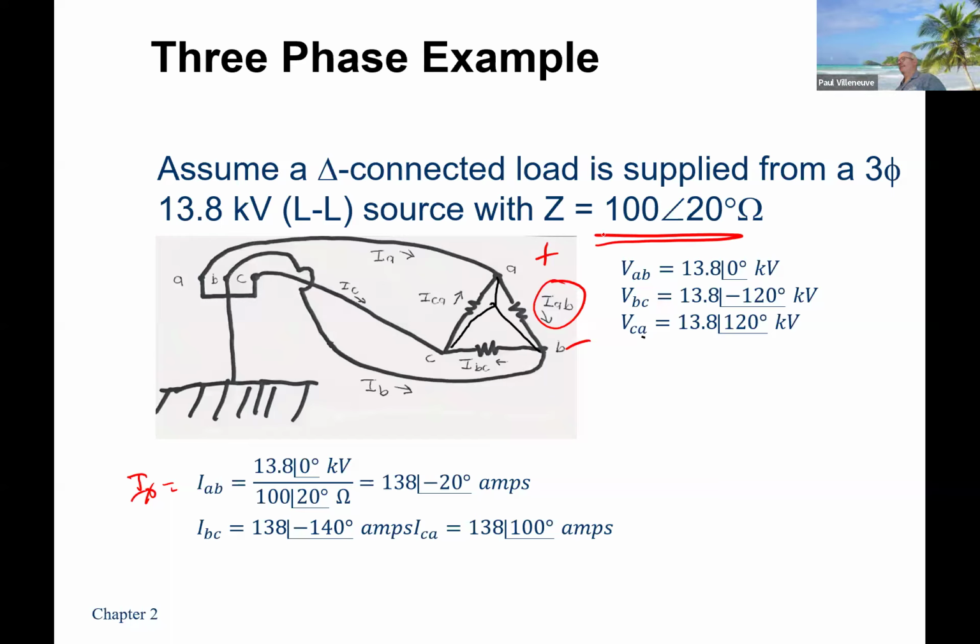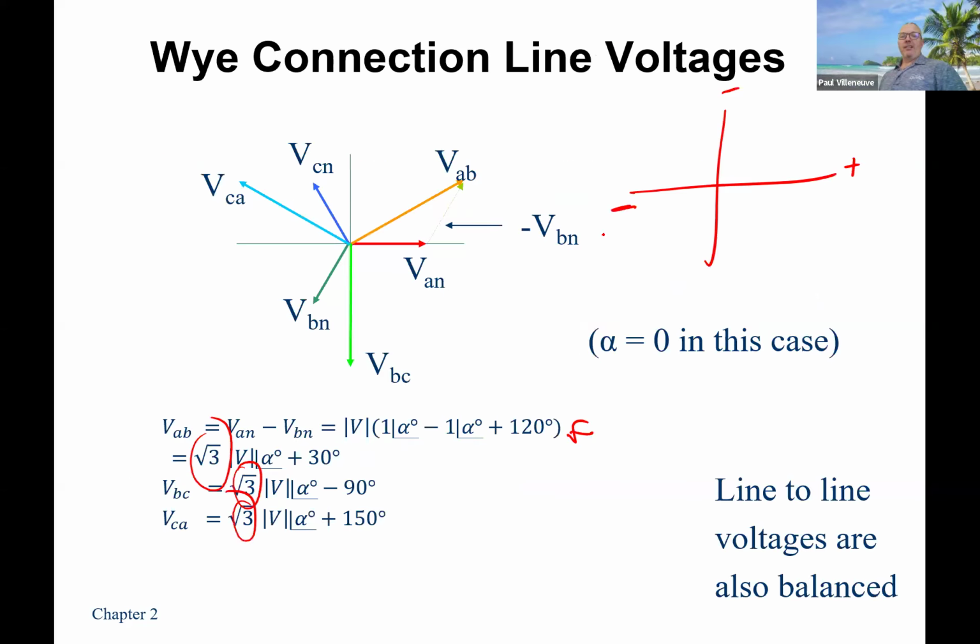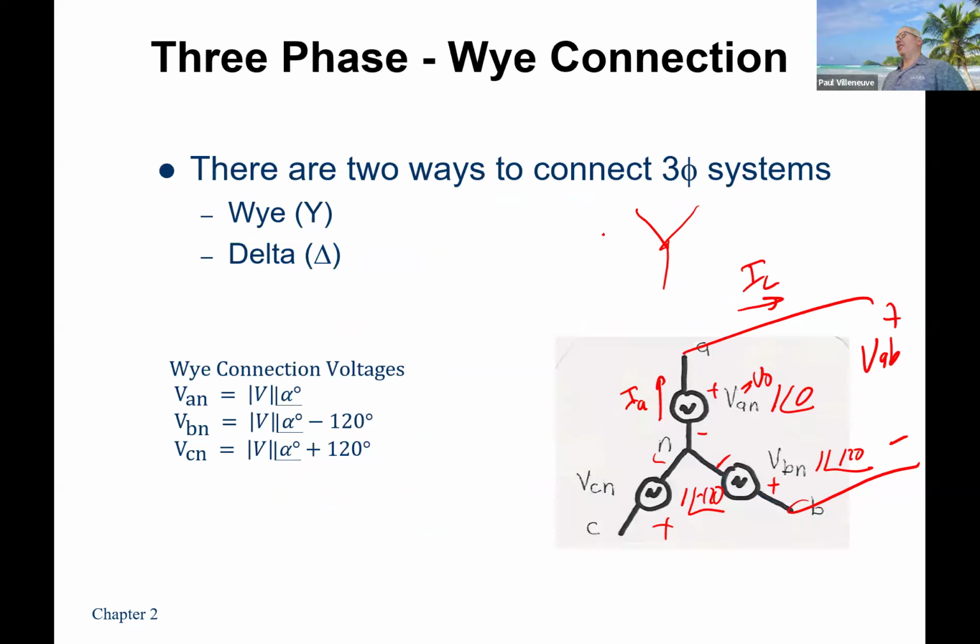Now, even the motor, right? Let's say I have a three-phase motor load that's 100 horsepower. The motor looks like 100 horsepower, but there are three phases inside the motor, separate individual phases that are interconnected at one point, and each phase is responsible for 1/3 of the rating. So each of those phases is doing 33.3 horsepower worth of work. So with all this stuff, we talk about three-phase. There's no such thing as a truly three-phase load. There's a three-phase source, but even when we look at it a little bit zoomed in, those are three single-phase sources just interconnected and set up at 120 degrees to get what we need.